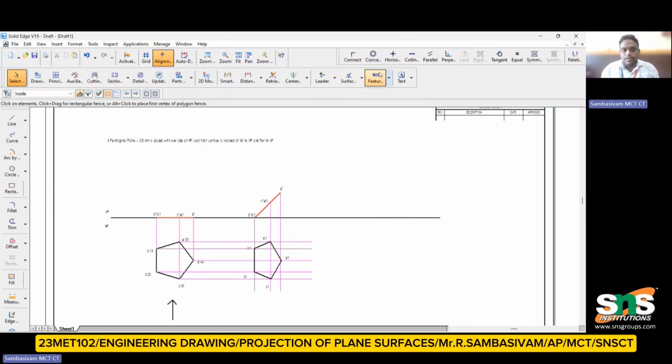The next part is to give the dimensions. When I click this surface, it will show 28 mm. Similarly, on any side we can see it is 25 mm. Then the total dimension of this one is 43.9, and this one is 43.09. This is the final view. Similarly, for understanding the angle between two surfaces, this one and this one will be taken into consideration. That will show 108 degrees.